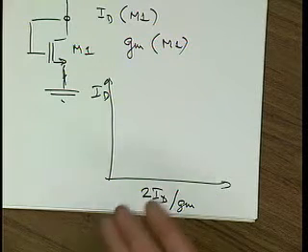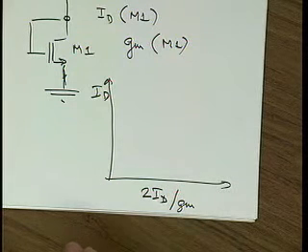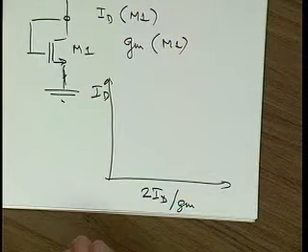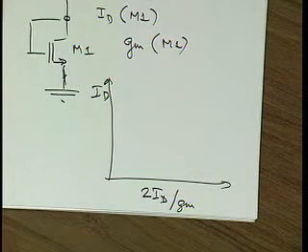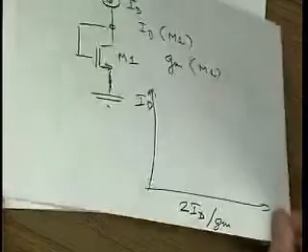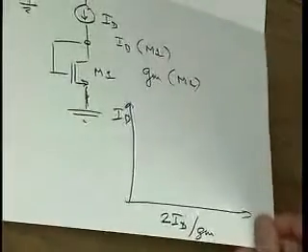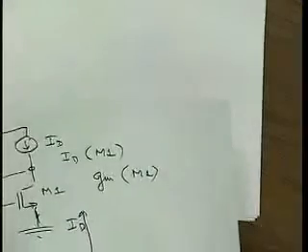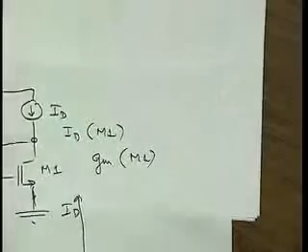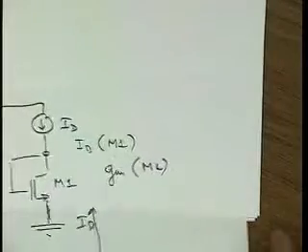And of course, then afterwards, we have to make sure that we don't get horrible impact ionization when we are 10% over at 3.6 volts or something like that. Okay, so these three curves are just to show the kind of variation we get on stuff like voltage gain.